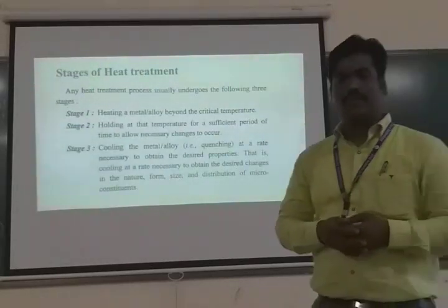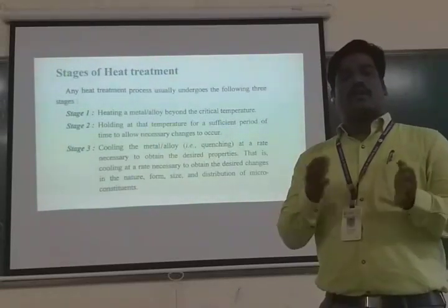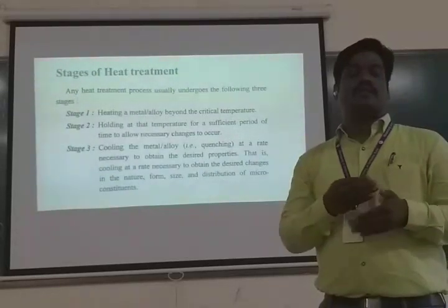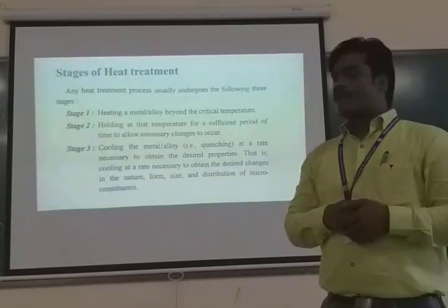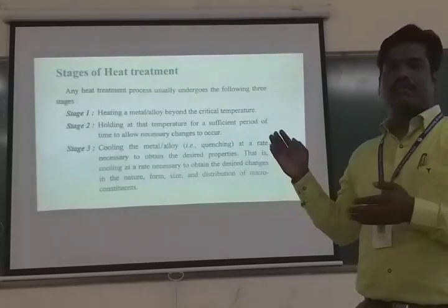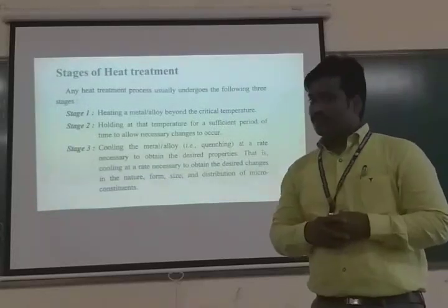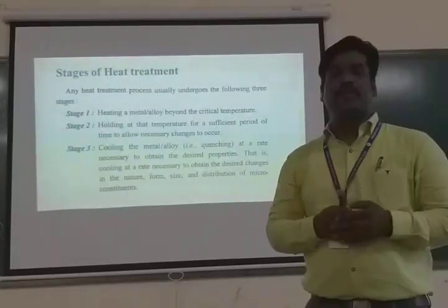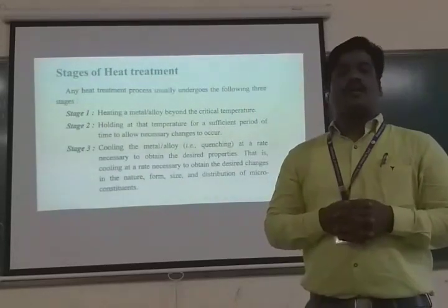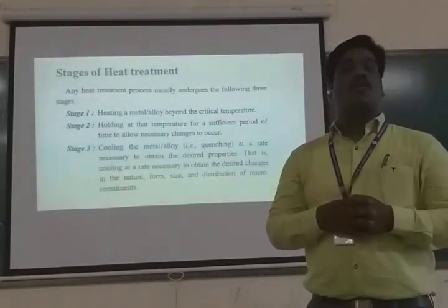The necessary changes occur in the sense that we need to retain a particular temperature for a particular time period, because we need to rebuild the material inside. So, holding at a particular temperature for a sufficient time period. The time period is given for different temperature regions, because the temperature regions play a vital role in this holding time period.